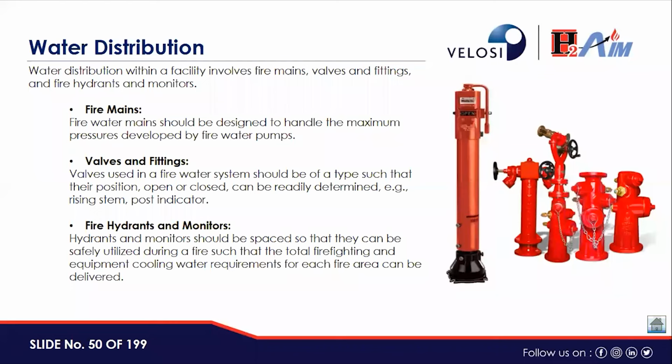Fire water mains should be designed to handle the maximum pressure developed by fire water pumps. Valves in a fire water system should be of a type such that their position, open or closed, can be readily determined, for example, rising stem or post indicator. And hydrants and monitors should be placed so that they can be safely utilized during a fire, such that the total firefighting and equipment cooling water requirements for each fire area can be delivered.